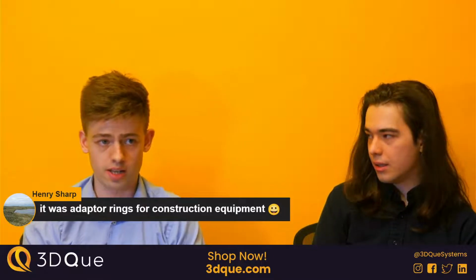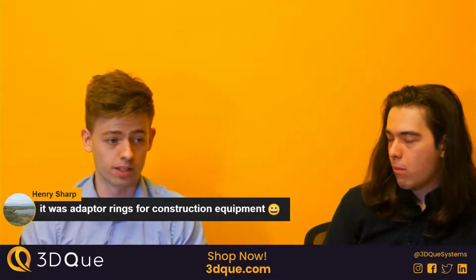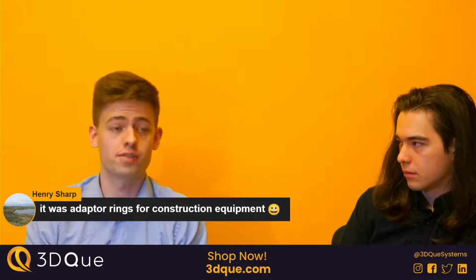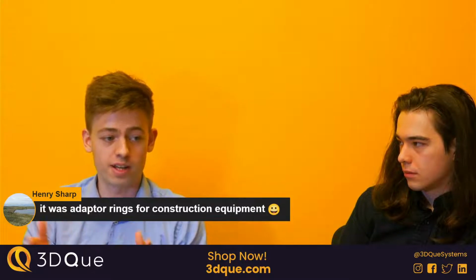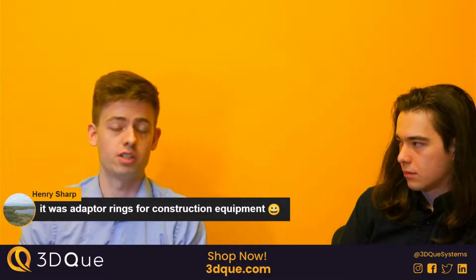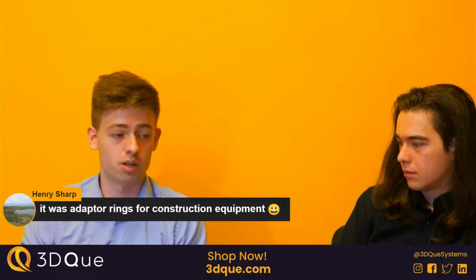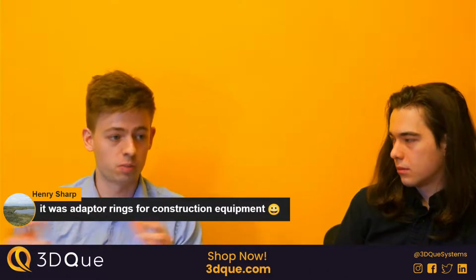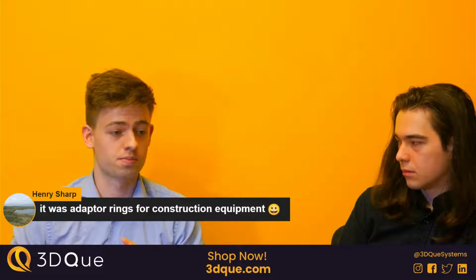It's a good use case for it, because if you know that you need to at least try out a few different fit sizes, or if you know you're gonna have to do a few iterations, you can create a few different files with slightly different dimensions, send them all into a queue, and then come back and try them all out and find the one that works best. Rather than the process of: okay, print one, try it, doesn't work, make a change that you think is gonna make it work.